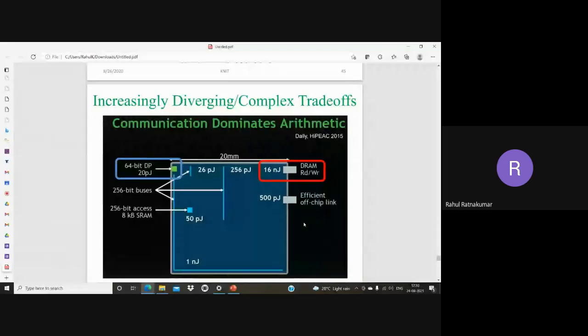And length is also increasing as our chip size is reducing. We have a lot of features, different cores, a lot of cores within one chip. So what happens? The length of the conductor is also increasing. A is decreasing, L is increasing. So resistance of the conductor is increasing. And as resistance of the conductor increases, I square R loss is also increasing.